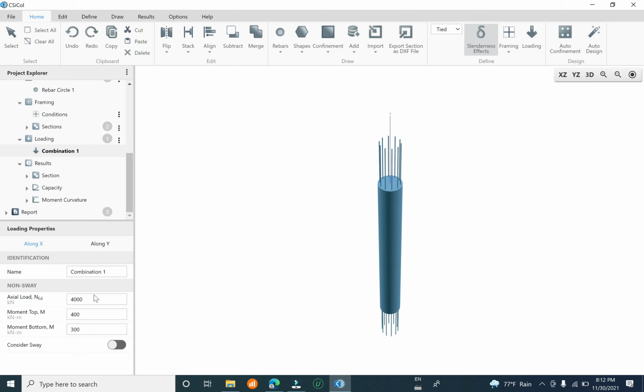You can check the displacement, you can check the comparison of the second order moment effect, or you can use the critical load factor in the Global FEM, or the Tekla Structural Designer also has this option to check.